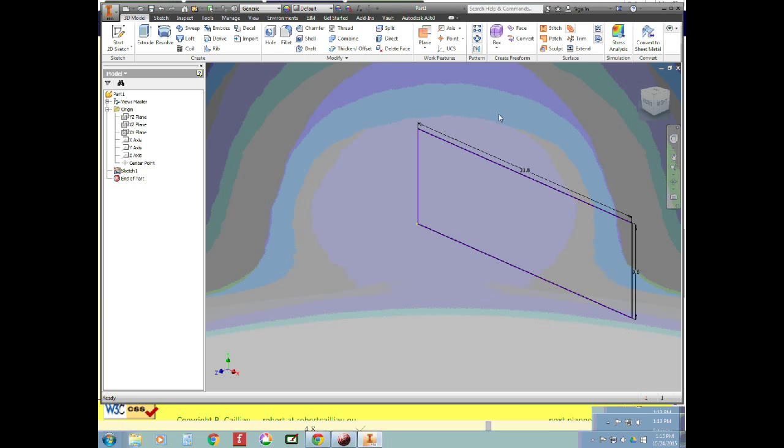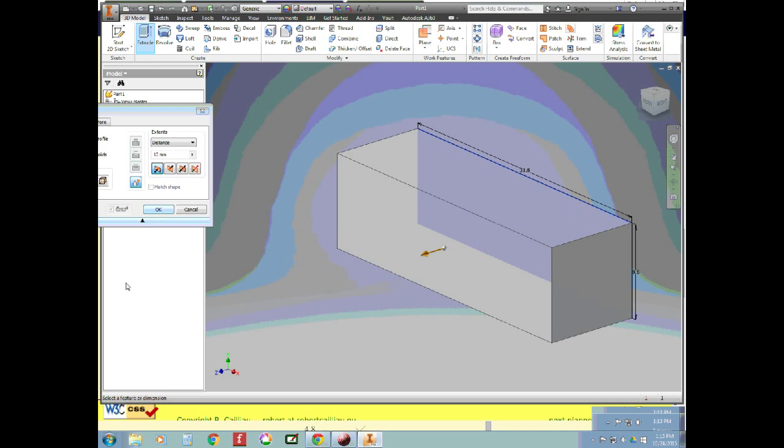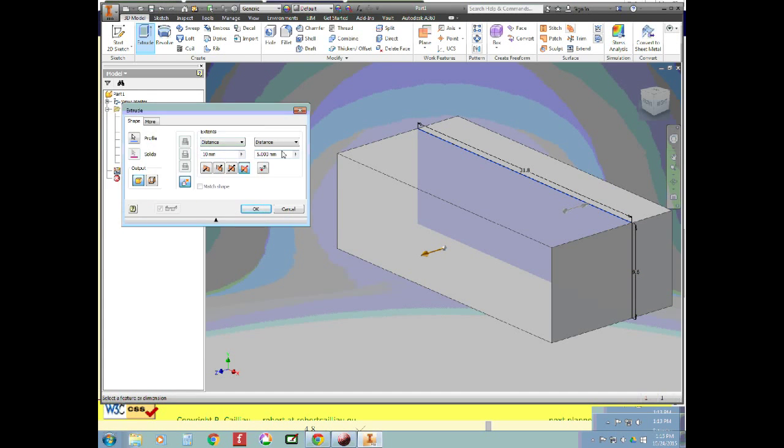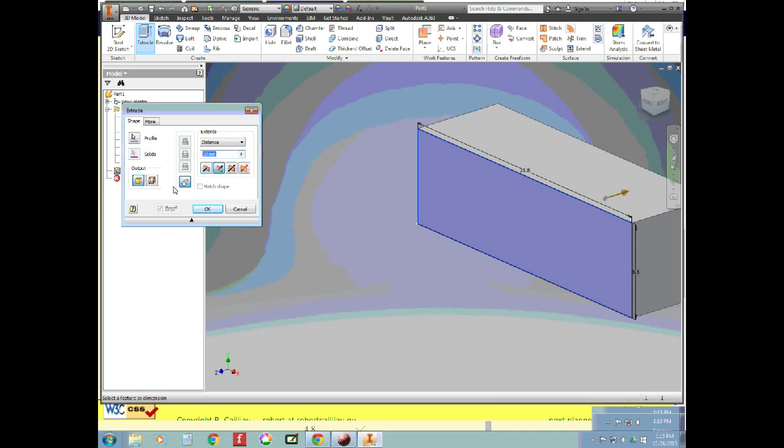So let's go ahead and choose extrude here. And I want it to go back into the screen. It's just a preference in this case. My nephew prefers having it extruded the same distance on each side. So this would be half of 15.8, and this would be half 15.8. For this, I'm just going to extrude it back 15.8 millimeters. And click OK.